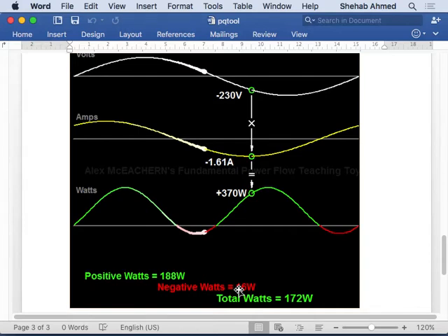Anytime you have flux in any physical device, the circuit representation of that is an inductor, right? And an inductor means that you have inductive or lagging current, which means you have reactive power in the system. It's there. Anytime you have a generator, it's there. Motor, it's there. Cable, it's there. Anything pretty much has some inductance to it. Fine. Power electronics based fluorescent lighting, you can make that unity power factor.